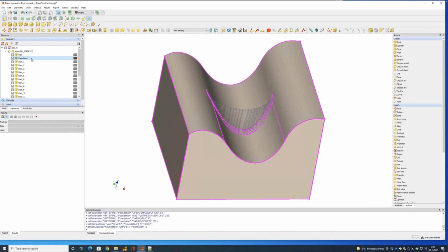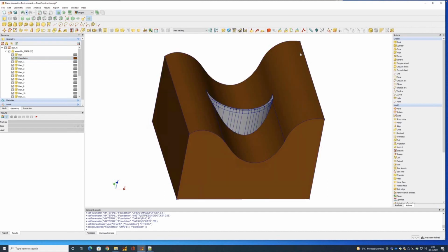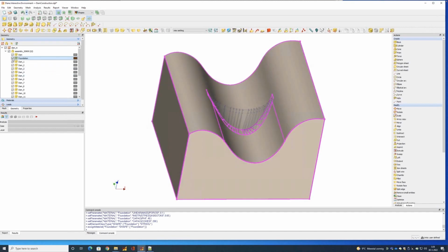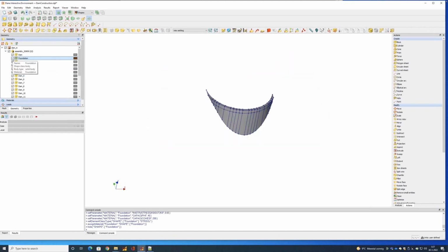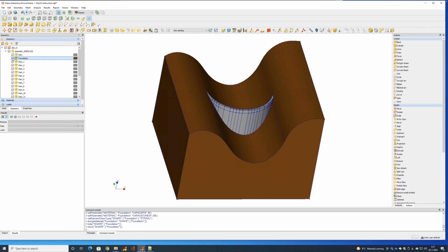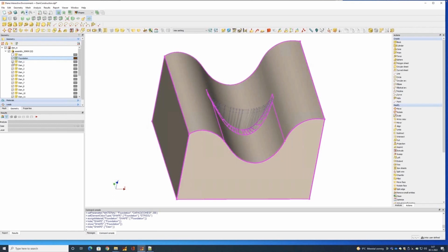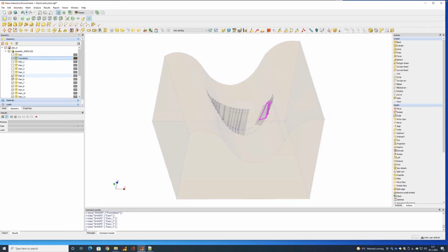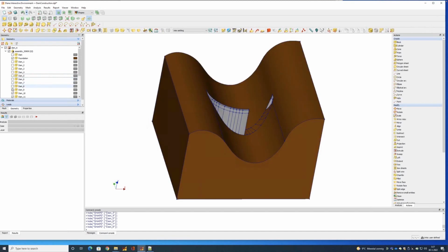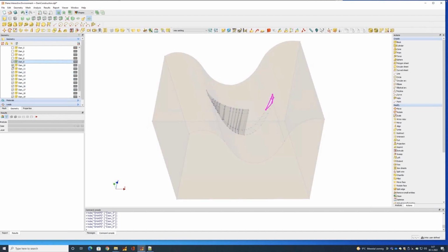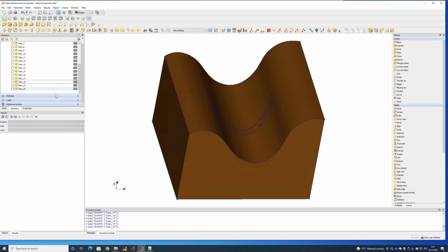And then we will select the bottom face of the dam segments, which will be the target. So we are going to do that. And first I'm going to hide the dam; I want to keep the foundation. It will make my selection much easier. So I hide my different segments, and I will bring them back in the next stage.